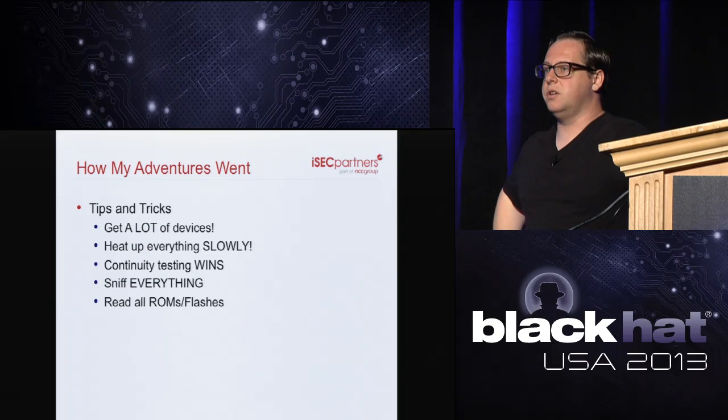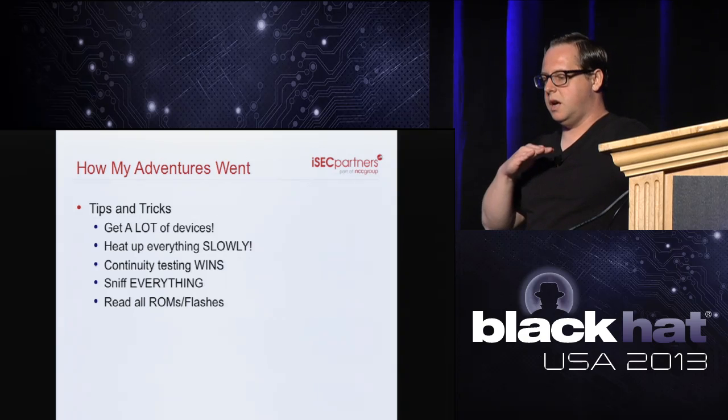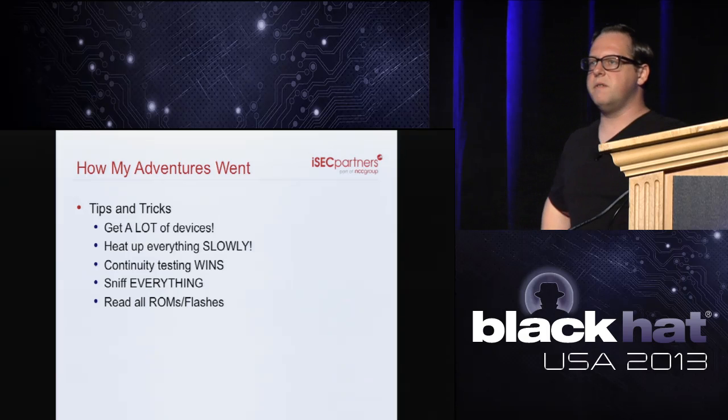Continuity testing, I couldn't have done all of the tracing of this without the continuity testing. It makes it so much easier to trace through boards and planes going through the board. Sniff everything that you find.